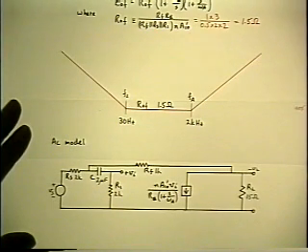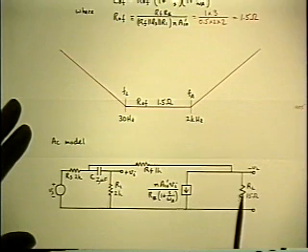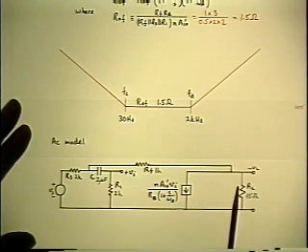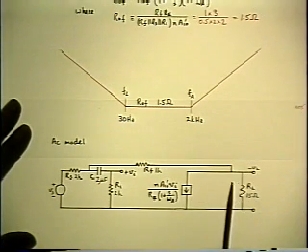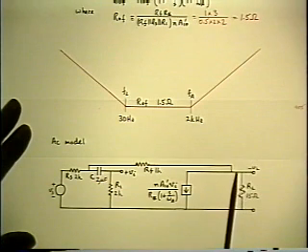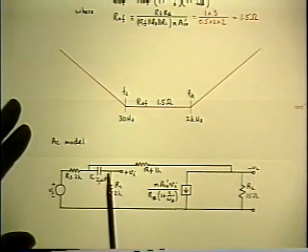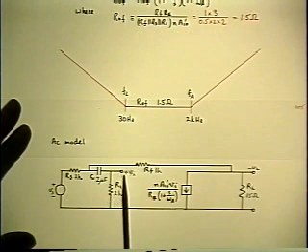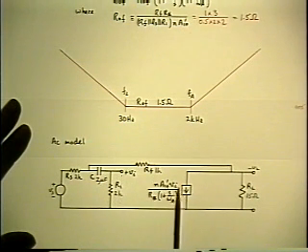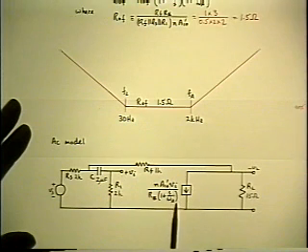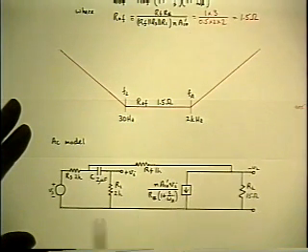Likewise, at infinite frequency, if you apply a test signal at the output, the signal would go down the feedback path, and the coupling capacitor would now be a short, so you'd get a non-zero VI, which would activate this generator, except for the fact that at infinite frequency, the pole would cause the generator to be zero again.